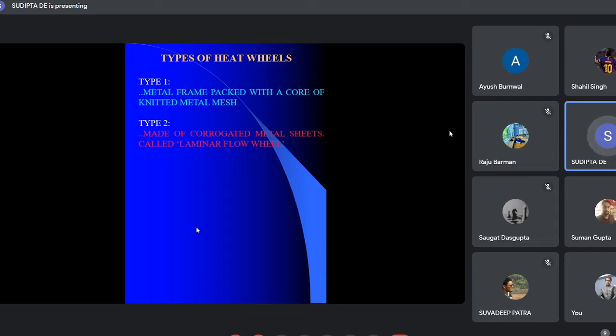but heat transfer characteristics and pressure drop both may be inferior than the type 1. So obviously the type 2 matrix is desired only for specifically high dust loaded gases.